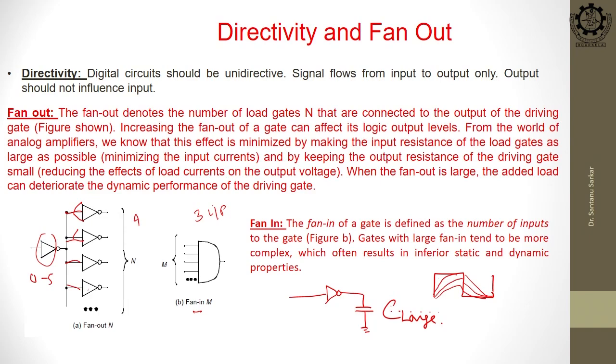That is why it is advised that you do not increase your fan out unnecessarily, okay. Actually what is happening is your delay is increased, or your signal strength is decreasing, and it may not be able to drive. So large fan out is not advisable. Similarly, large fan in is not advisable. Can you tell me why?